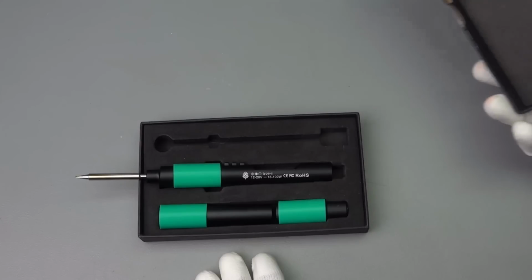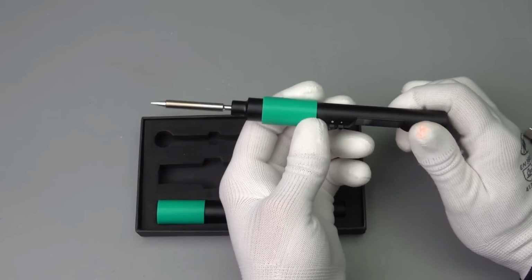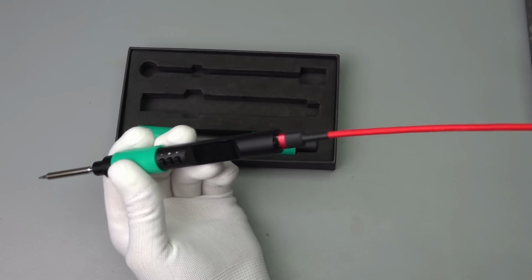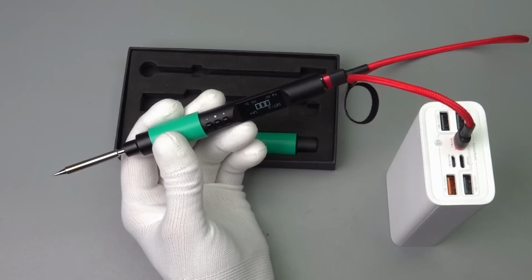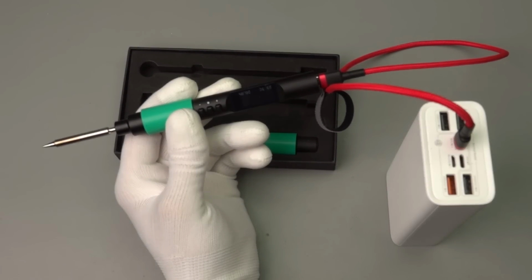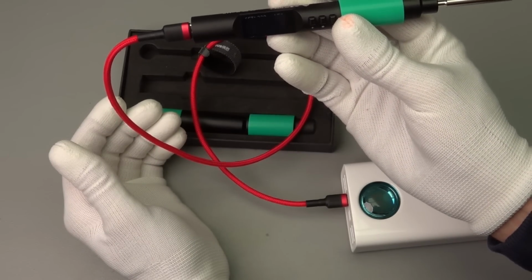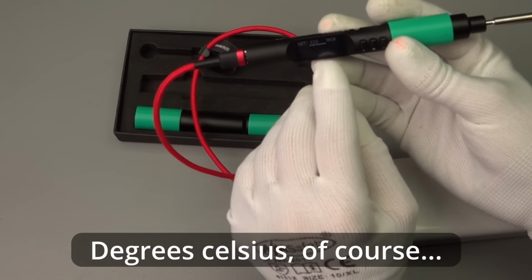Next is this PTS200 soldering iron. I already put it together, and it also has a USB-C connection, and it also has power delivery like that. And you see it already works. And this is also important here, that this power bank can deliver 20 volts, because if I start it, it heats very fast, up to 320 degrees. This is now already at 320.